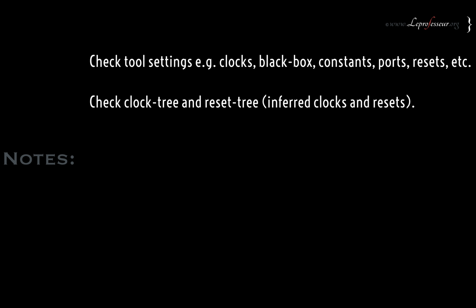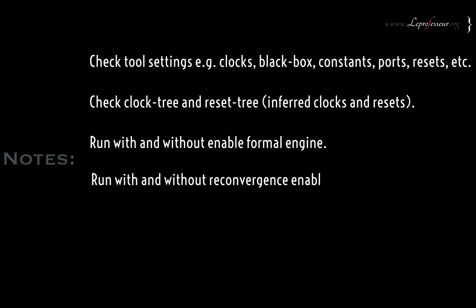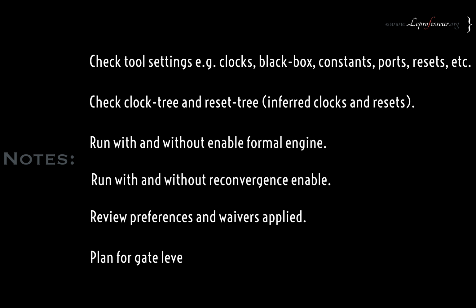Check the clock tree, reset tree, and if there are inferred clocks and resets. If there are inferred clocks, make sure that you have proper clock definitions in your clock file and all the clocks are properly captured. Very important. Run the tool with and without enabling the formal engine. Run the tool with and without the reconvergence enable settings. Review preferences and waivers applied.